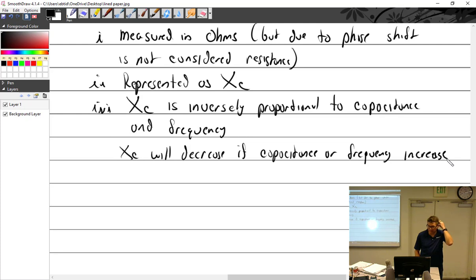And I go back to the same thing, go to extremes. If you have a sine wave that is very, very slow, your frequency is extremely slow, it's like kind of reversing once every few minutes. That is going to be a lot of capacitive reactance. But if it's going very quickly, then it acts like it flows through the capacitor much easier. Or if you have a larger capacitor, it looks like it flows through it a lot easier. So you lose the X of C.